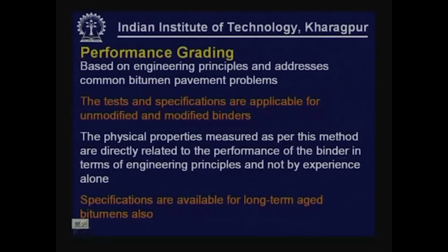So, this is a more complex system requiring more complex testing procedures. However, in spite of all the complex methodology and costlier equipment that one needs to use, this is considered to be very rational. The properties that we determine in this procedure are better related to the performance of the binder in terms of engineering principle, and not just simply by experience. These specifications are available for long term aged bitumens also.